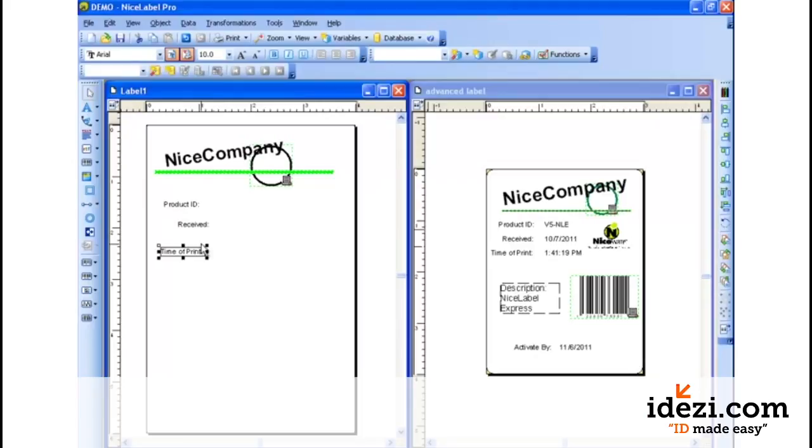There is an easier way to do that. Let's select all three of the text boxes and we'll go to the right hand side of the toolbar. Here we can align it to the left, and then we can space it evenly vertically. That looks a lot better.